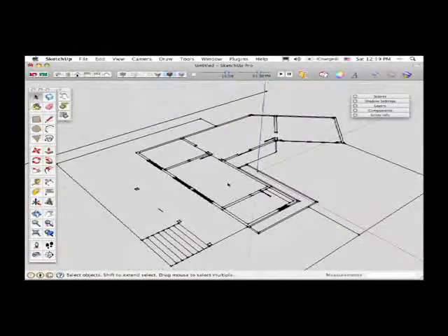I've also seen CAD drawings that come in from Vectorworks that were drawn to scale, and again you get that scaling issue where the drawing comes in and it's at 1/4 inch scale. It's this itty bitty tiny drawing and you have to scale it up. So rather than undoing back and going through that whole import process all over again, I just want to show you a quick trick using the tape measure tool to getting this drawing down to the right scale.